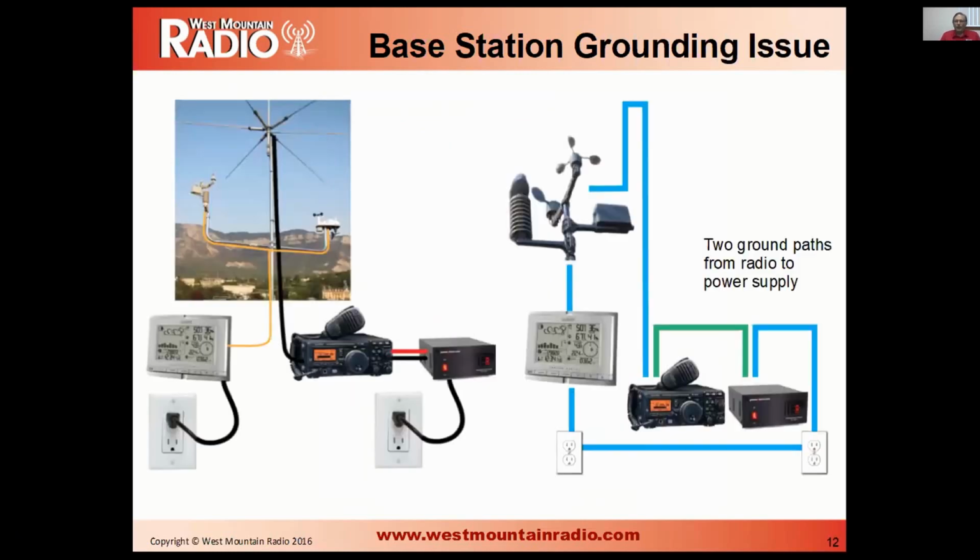Here's the issue. If you look at the diagram on the right there, the intended path from the power supply is that little green line there. But you've got a second ground path from the power supply. It goes into the wall, through the weather station, up the mast through that telephone wire, and then to the ground on the mast. So that blue line is a secondary ground path. When you key up your radio, half of the current is going to try and go through the blue path, and that's going to vaporize the telephone wire.